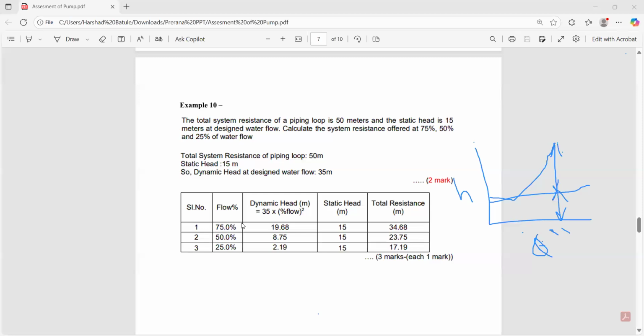There is no resistance in the pipe, but if your water level is more than your pipe, there would be resistance to get into that particular pipe. So that's a dynamic head. If your flow rates are on the higher side, your dynamic head, frictional head are going to increase.